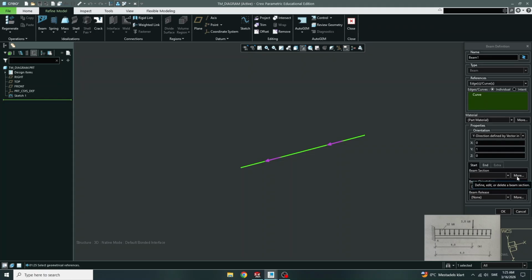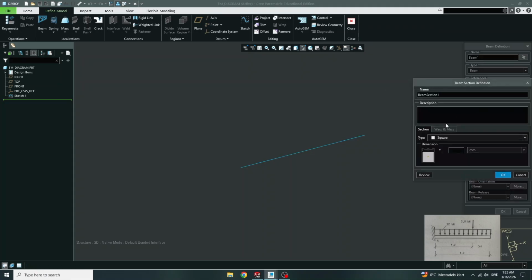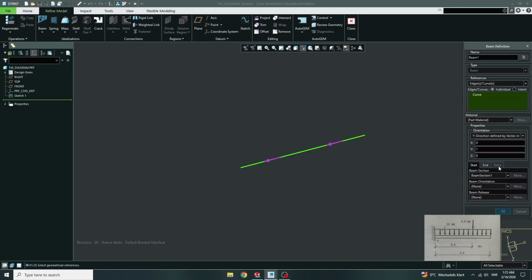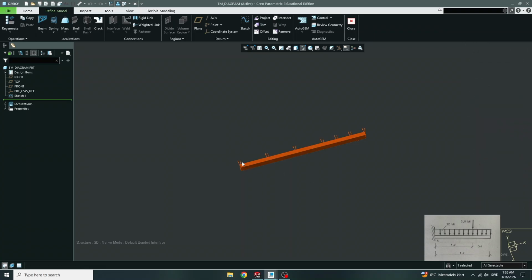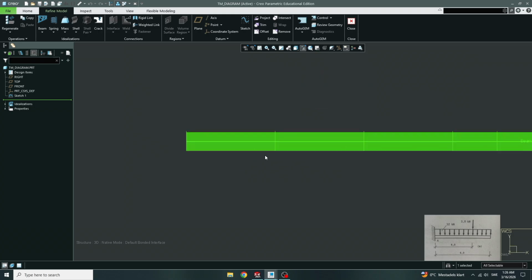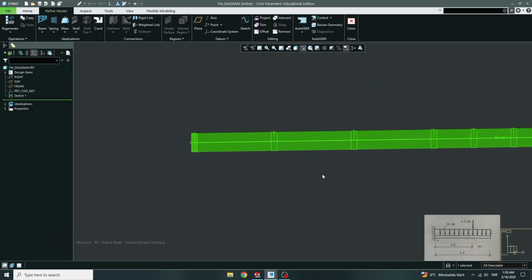and for the beam section or cross-sectional area, you go to rectangular, and then you choose 200 for the cross-section and 300 millimeters, and you press OK. Beam section orientation, you can rotate it if you want later, but let's look at the plane from the front side. Yeah, I guess it's okay.